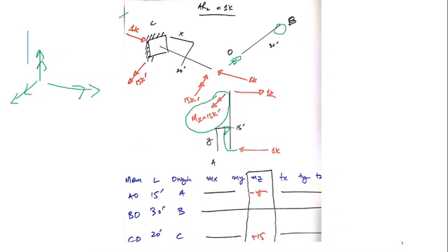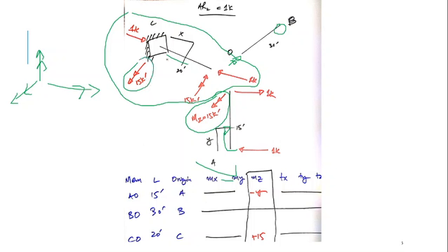Now I have to balance this member, which can be easily balanced. You know that 1 kip is in this direction, so I'll apply 1 kip rightwards and it would be balanced. This member is in X direction, so there would be no moment. This 15 kip foot would be transferred here because this is clockwise. So I have applied an anti-clockwise moment in Z direction because this support can take moment. This is a fixed support, so this moment has been transferred as it is.